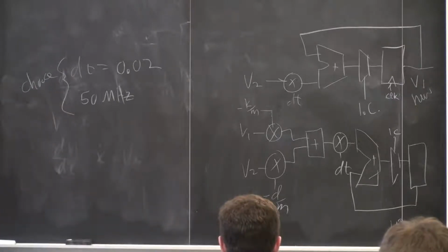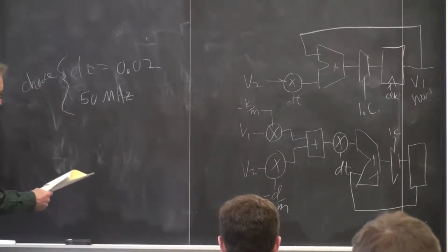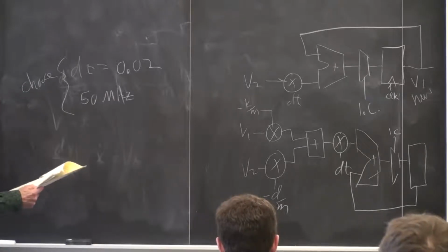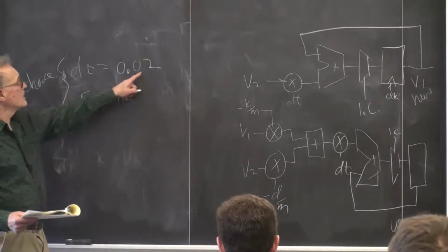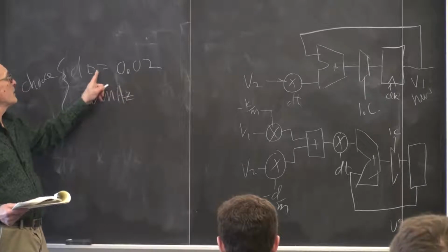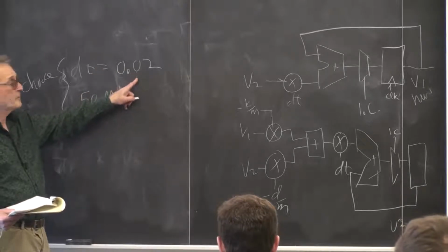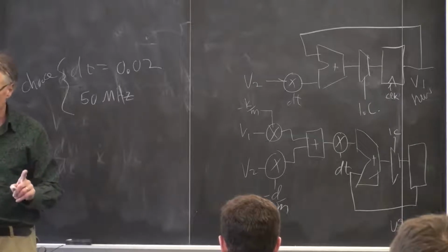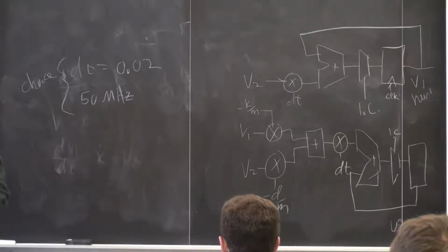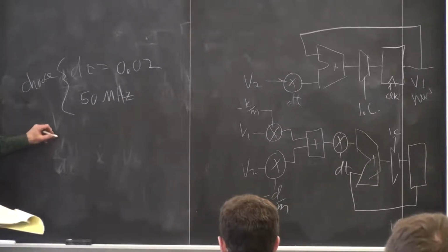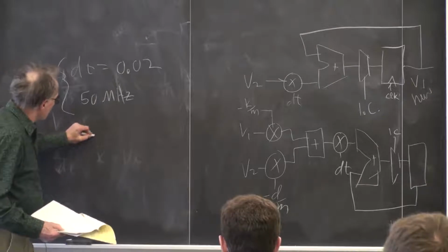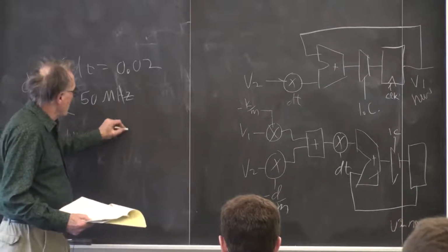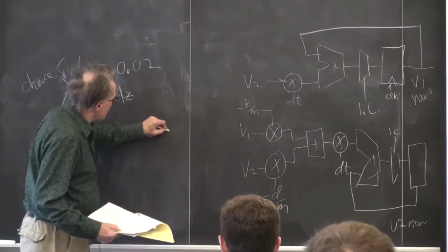that says that the unit time must be 50 times longer than this value. If you're updating at 50 megahertz, that means that the unit of time in real seconds is 1 microsecond. 50 steps at 50 megahertz. So the real time unit is 1 microsecond.